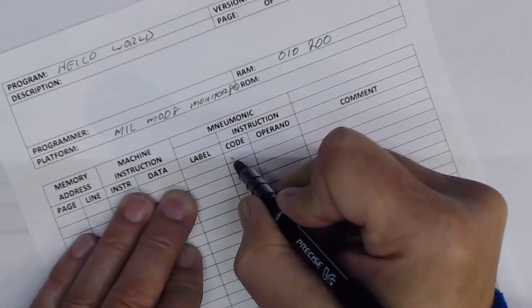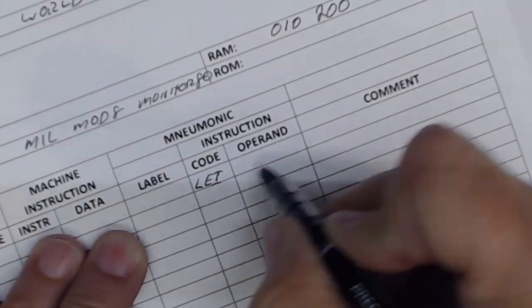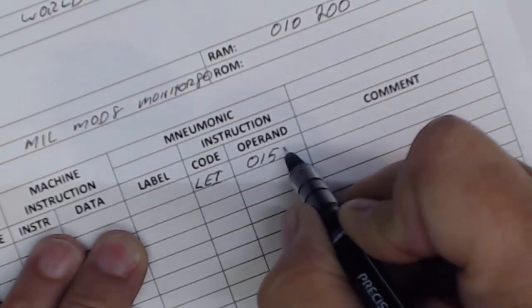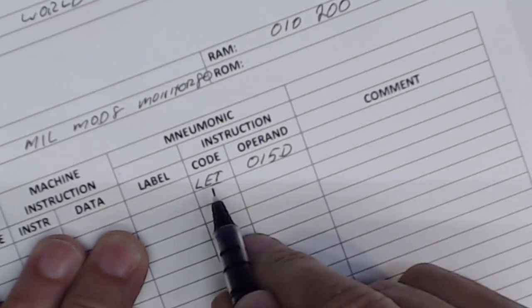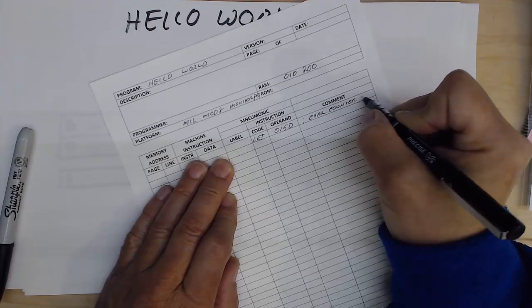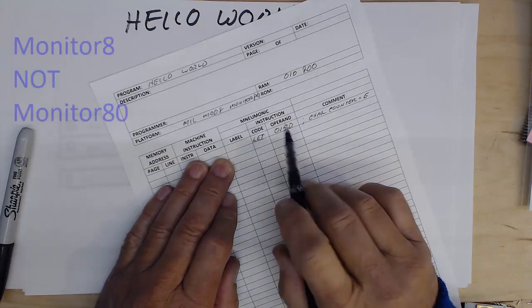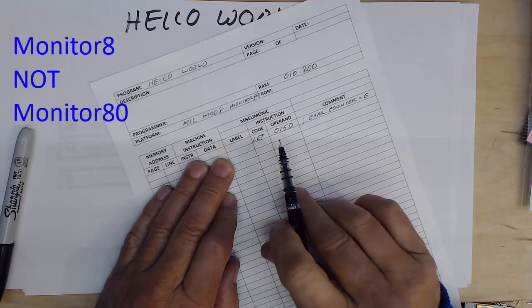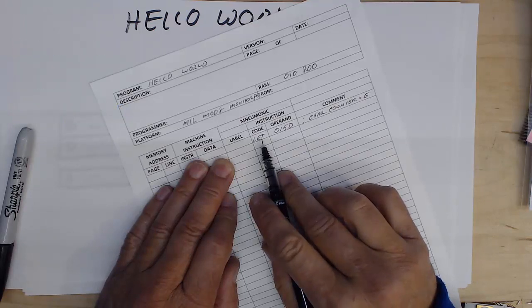The first thing that we want to do is load into register E immediate the 015 decimal, and this is how many characters we're going to output. We're going to put our counter in register E. The reason we're using register E is because later, when we use the routine in the Monitor 80 that sends that out to the teletype, it destroys registers A, B, C, and D. The only registers it doesn't destroy are E and the HL pair.